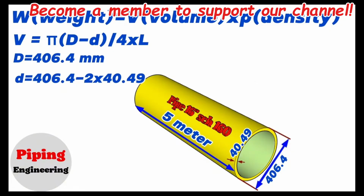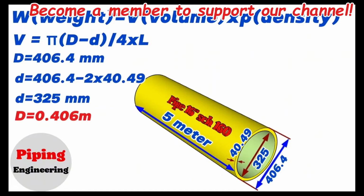So, the inside diameter of the 16-inch schedule 160 pipe in our example equals 325 millimeters. These dimensions should be converted to meters also. Then, the outside diameter of the 16-inch pipe is 0.406 meters and the inside diameter is 0.325 meters. We also know that the length of the pipe is 5 meters.